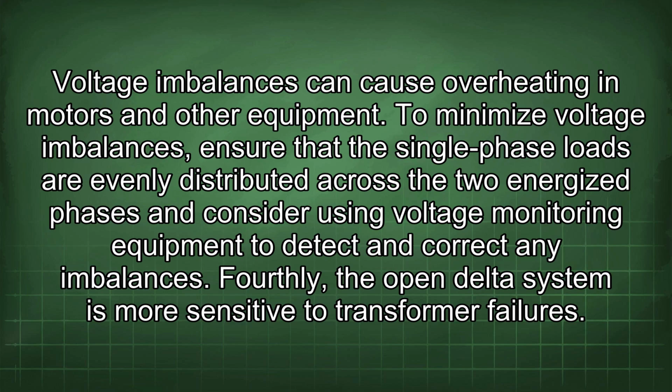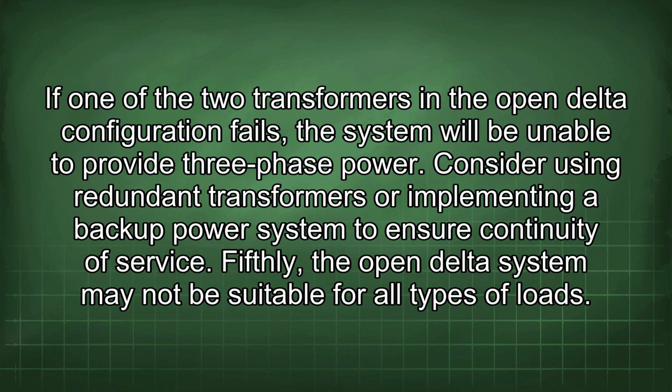Fourthly, the open delta system is more sensitive to transformer failures. If one of the two transformers in the open delta configuration fails, the system will be unable to provide three-phase power. Consider using redundant transformers or implementing a backup power system to ensure continuity of service.